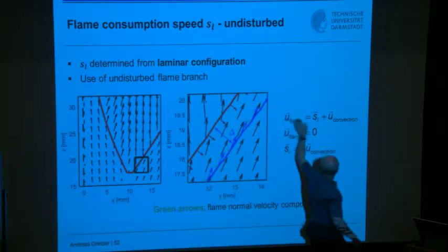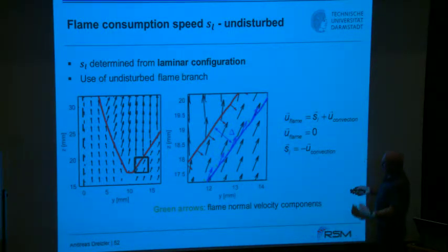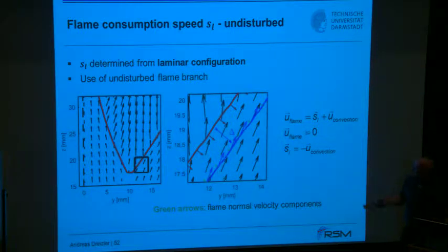You put that in here, and then you find, and you know that from combustion classes, I guess, when you have a stable Bunsen flame, for example, then your laminar flame speed must compensate the approaching convection speed. And so you now take, at this blue line sufficiently far from the real flame front to avoid density effects, for the same reason, the flame-normal component, these small green arrows.